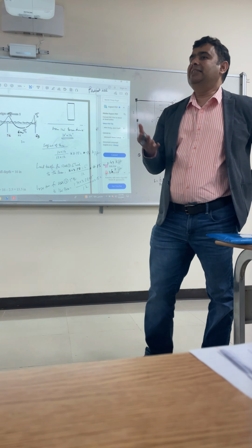So just calculate the total dead load which is acting on the beam. The first one is the self weight, what you calculated, 0.14 plus 0.49 plus 0.49 plus 0.36. How much is coming? 0.99, so 1 kilo per feet. Clear? This is the dead load.